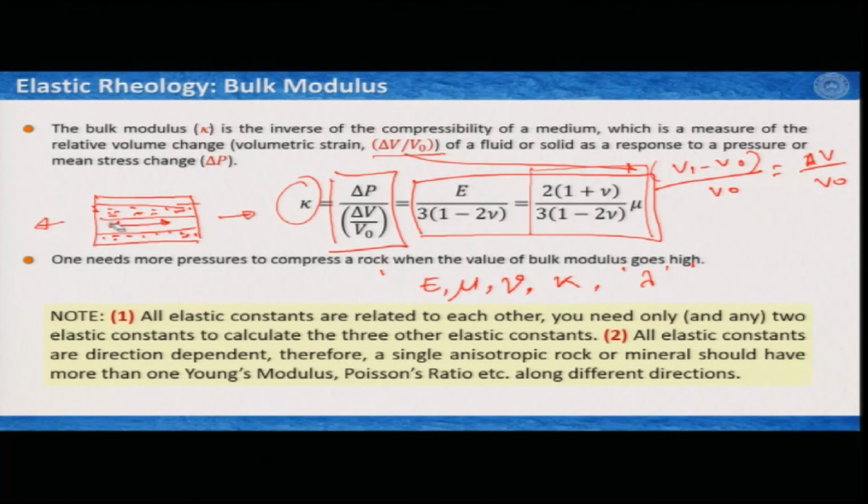But if I extend it along this other direction, I would get the Young's modulus along that direction. Because this is anisotropic, we have two different materials. So, if I consider this one as E1 and this one as E2, this is also a measure of the elastic anisotropy of this rock in terms of Young's modulus.